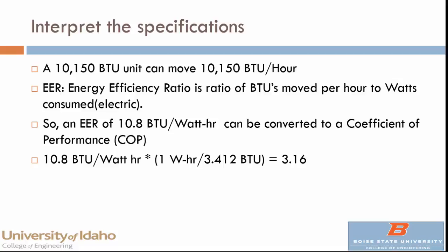That can be converted to the coefficient of performance if we know that there's 3.412 BTUs in a watt hour, so that means our coefficient of performance is 3.16.